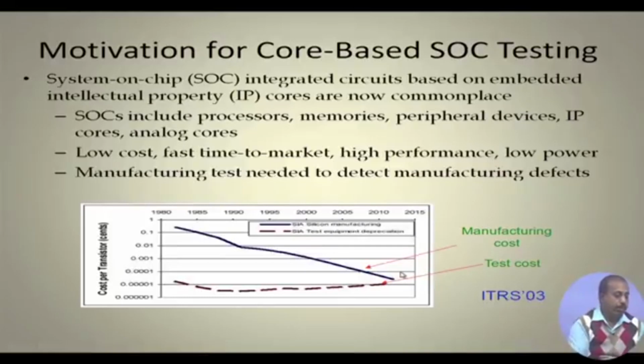That is because ATEs are becoming costly. If we want to test more and more chips at high frequency, the ATE costs are going to be high. The complexity and the amount of test time to be devoted are also going to be high, which translates into the cost of the system. So test cost is going to overcome the manufacturing cost.